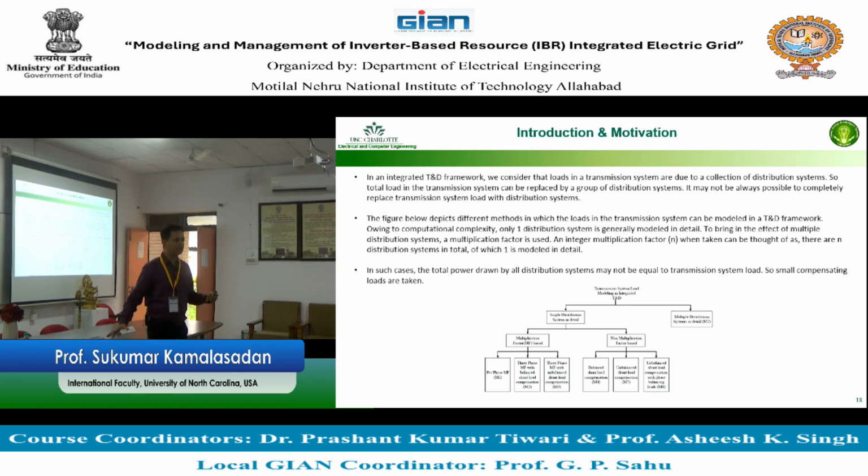Will you connect all 5 distribution systems, which is 7,000 node or 5,000 node, to the transmission system, which is 35,000 node, going into one point on a transmission system, which is huge? Or will you get an aggregated distribution system, one in detail and the rest comparable to the total at that point, and then add? Okay? So that's basically the complexity.